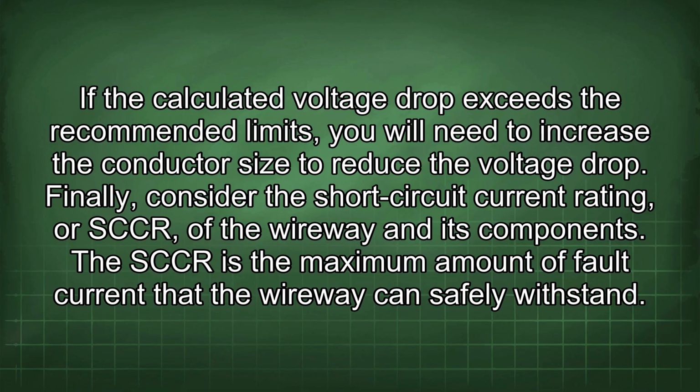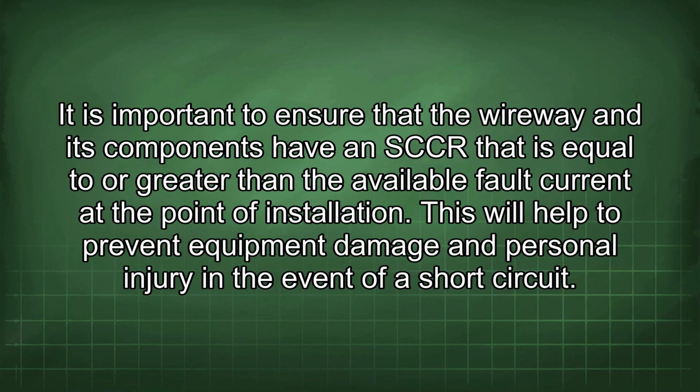voltage drop. Finally, consider the short circuit current rating, or SCCR, of the wireway and its components. The SCCR is the maximum amount of fault current that the wireway can safely withstand. It is important to ensure that the wireway and its components have an SCCR that is equal to or greater than the available fault current at the point of installation. This will help to prevent equipment damage and personal injury in the event of a short circuit.